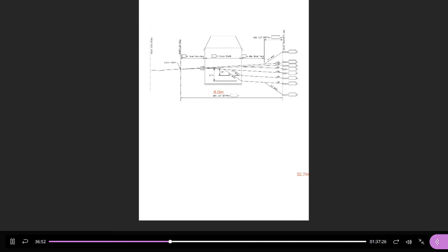Now, the building itself might be closer to the right-of-way, but not much closer. What I want to make sure is I'm at least at the front of the building. Doesn't matter. We're designing from one corner at the front to the corner at the back. Okay? We're not designing the middle. We're designing the sides, the edges. Okay? So the length along the lot line. So in AutoCAD, there's lines between the lots. If you list it, it tells you how long it is. That's where the 32.7 comes from.